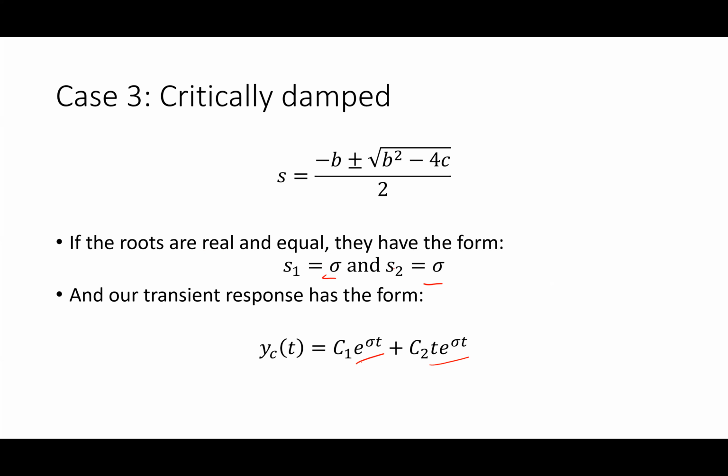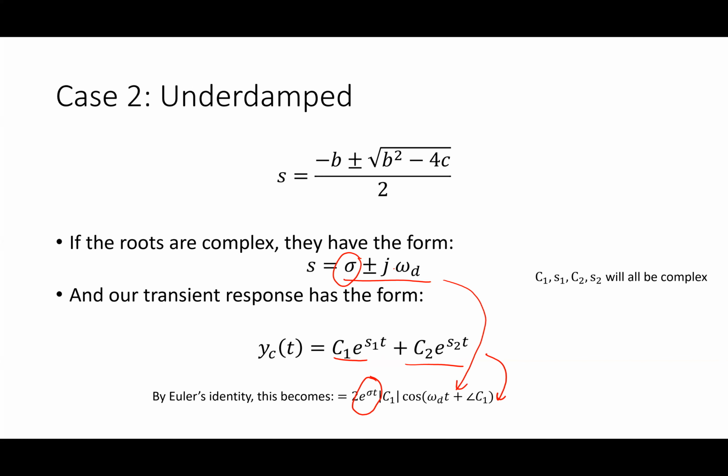They have to be negative. If the real part was positive, it would grow, and I'm violating the laws of physics. All the laws of the universe would be violated, but only for a very brief period of time until everything blew up in the circuit or whatever the system was. It's like the black and white videos of the bridge that's shaken in the wind, and eventually it breaks apart. That bridge has an oscillation that's trying to grow, and eventually it just collapses.